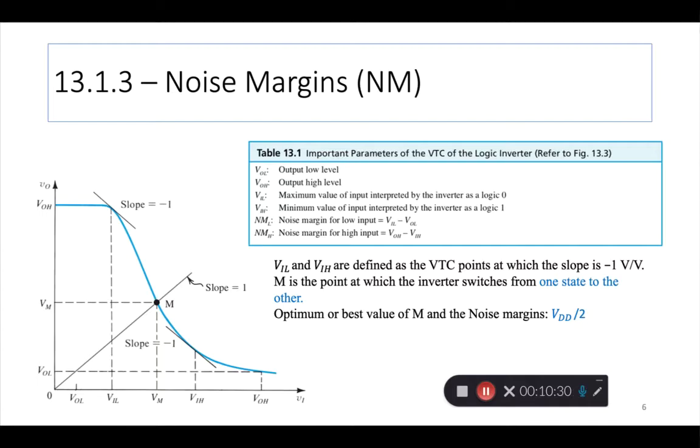The higher the noise margin, the better, because that way, of course, not too much, but you want anything that looks like a low to be swept into the inverter, to be treated by the inverter as a low, right? And because circuits cannot be designed to always have exactly the voltages that you desire, like you might desire VDD 5 at a certain point, but you're only getting 4.7, 4.6 because of drops here and there. Similarly, on the low side, you're aiming for 0, but you're always getting 100 microvolts or 100 millivolts or something. So such small tolerances above and below the limits, also you want it to be useful, right, and not be rejected. So that's why having higher noise margins is considered a good thing.